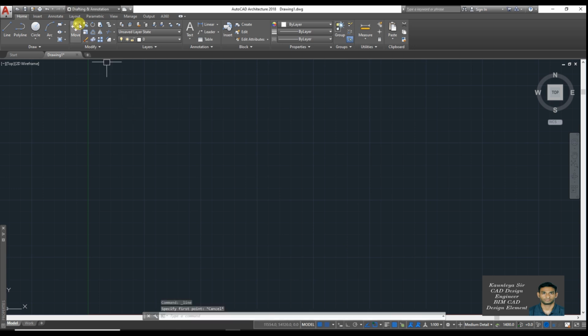If another type of command is applied, for example now we are here in the draw command, if I go into the modify command, the crosshair will again change, and when I escape it will return to its by default position. Then again if I select a text, it will again change, giving me some other graphics as you are seeing on the screen.